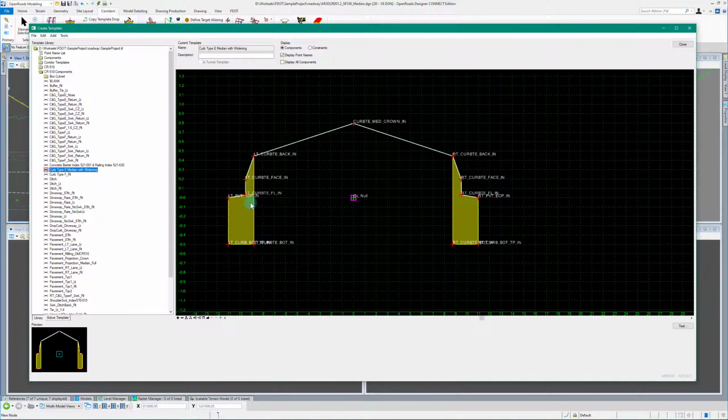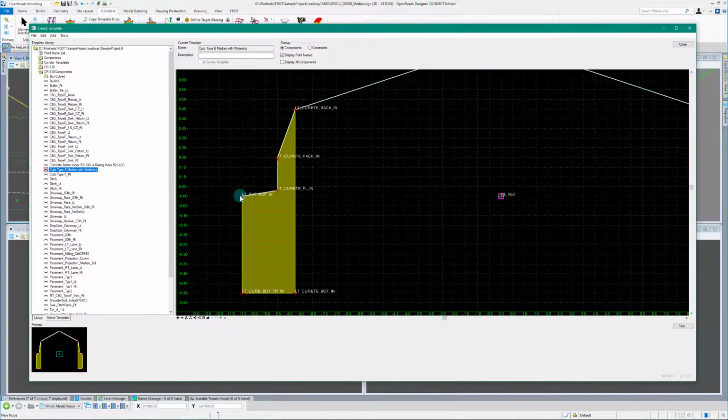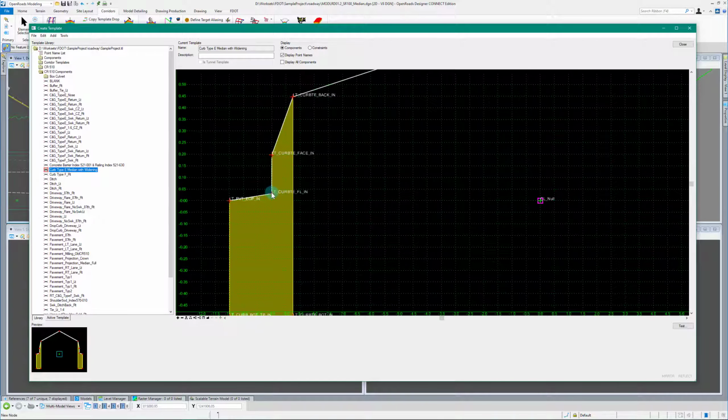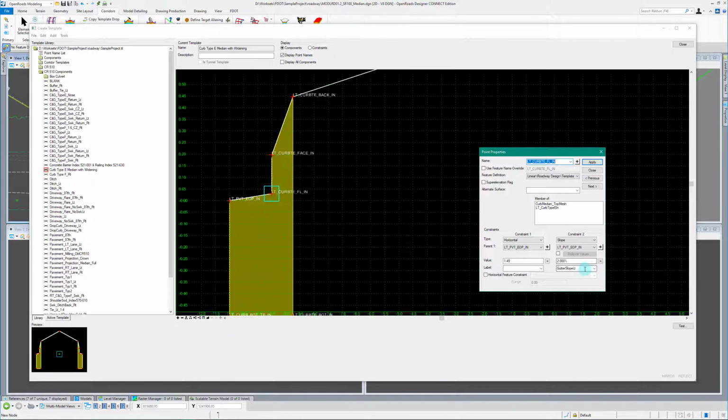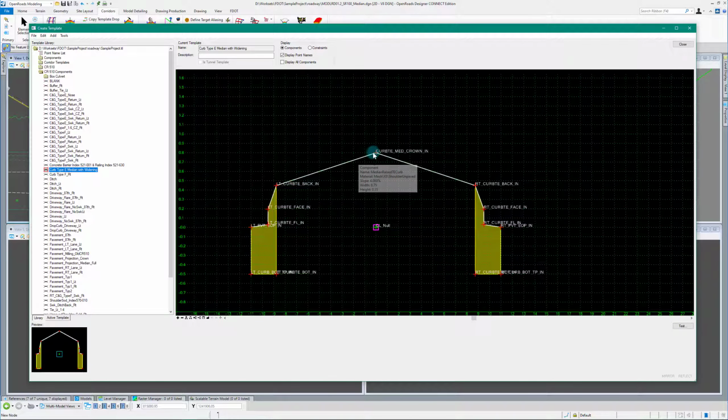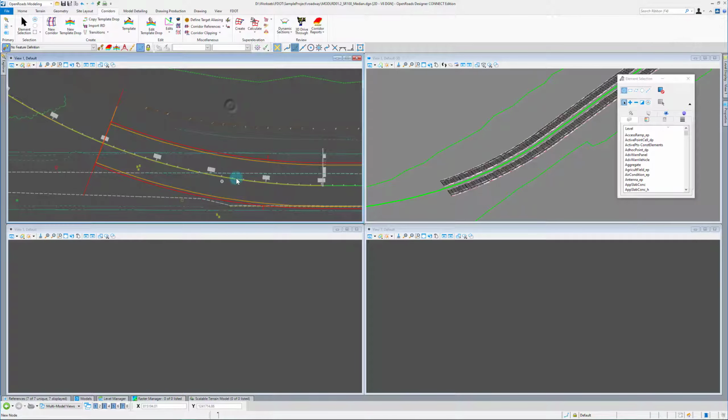So we'll draw our E curb. We have our inside E curb so that the gutter slope is matching the edge of pavement slope, and if we need to, we can come in and set a parametric constraint to be able to change that gutter slope if this ever changes. And then we just have our 4% up and down for our median. Pretty simple. So we're going to follow that same thing.